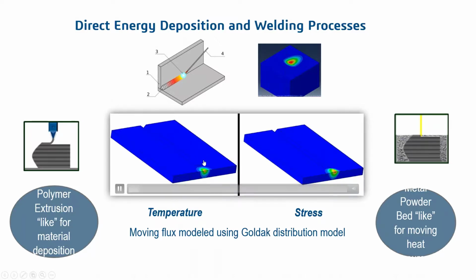And this is what we see on the left-hand side here. The weld simulation would first be a temperature or thermal simulation where material is added, free surfaces are calculated, and radiation and heat exchange with the ambient are taken into account. This would give us the thermal history.